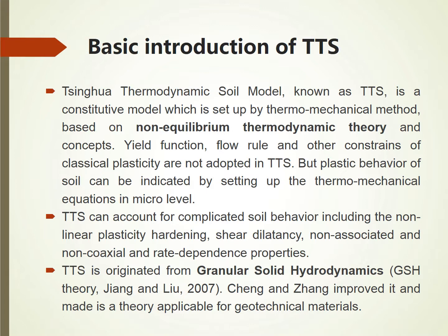So I will give a basic introduction of TTS. I know someone here is also doing some research on this constitutive model. The Tsinghua Thermodynamic Soil Model, known as TTS, is a constitutive model set up by a thermomechanical method based on non-equilibrium thermodynamics theory and concepts.